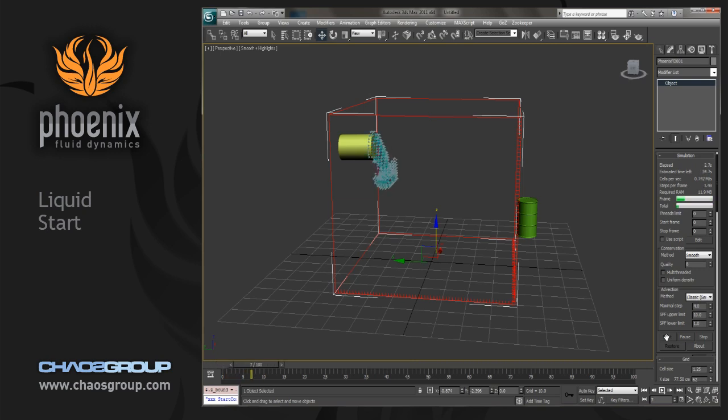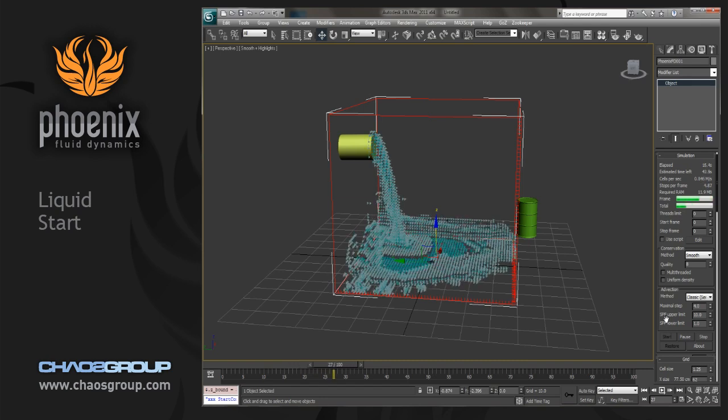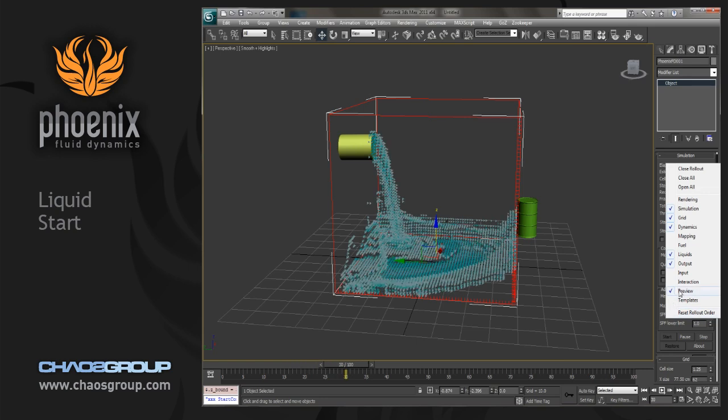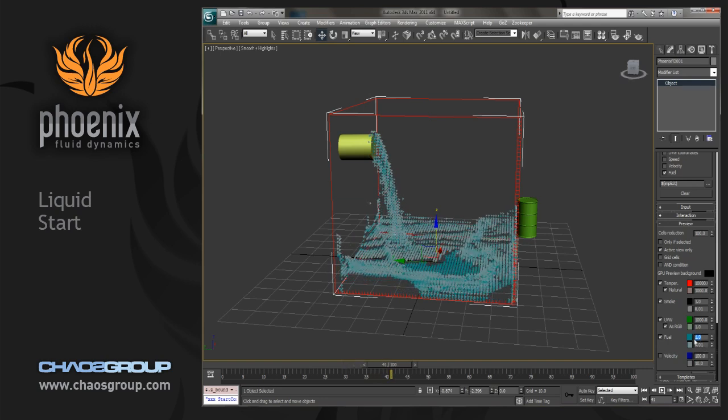Now when we click simulate, this fluid's going to come down, the liquid will hit the floor, and it's going to start spreading up, ripple and start pooling and things like that. So we can watch this simulation happen. And while we do this, I'd like to take the opportunity to look at the preview. You can see right now under preview, we're previewing the fuel between 0.01 and 1, and those are the two colors we get.